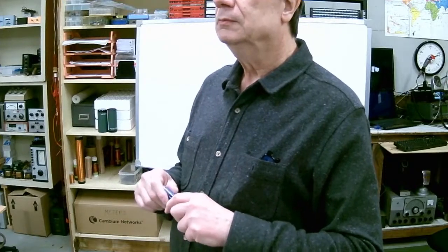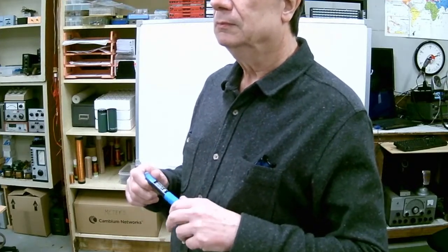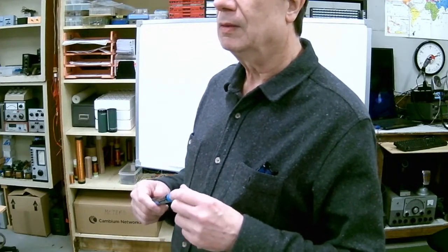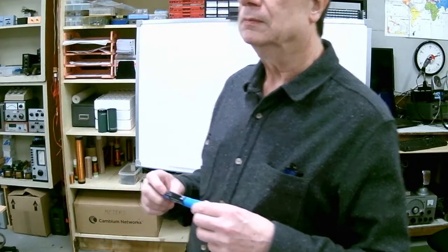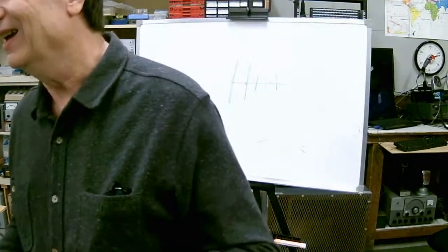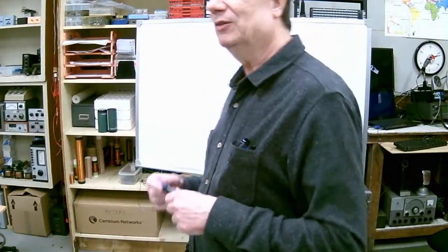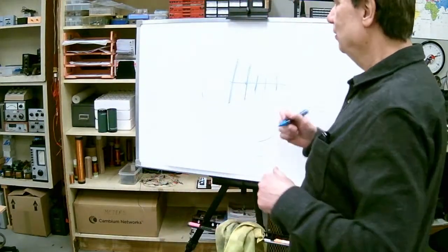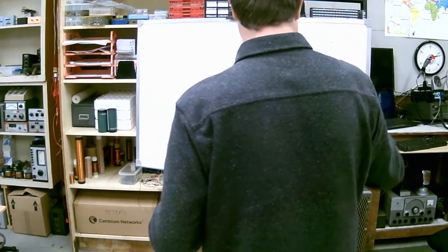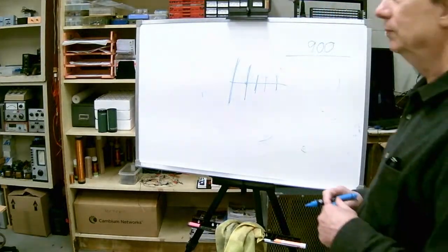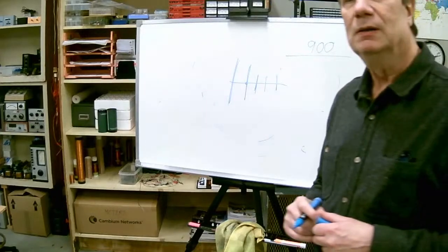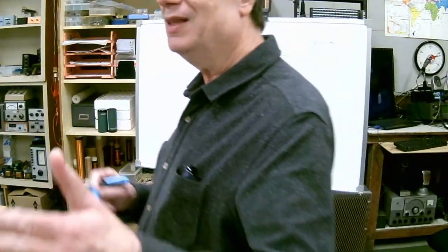So how do you get the length? Just for my simple brain, because we did 7 megahertz, that's 7 HF. 300 million divided by frequency gives wavelength. So this is 900 megahertz, so wouldn't that be 900 million? So you divide 300 million by 900. It's going to be a third of a meter, about a foot, 12 inches. But you cut it in half. That's one wavelength, so you take half of this.